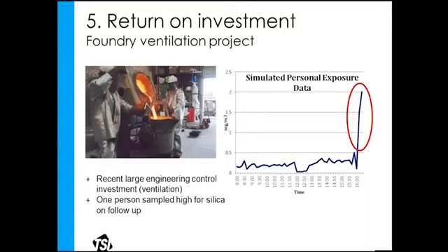And so he was the hero. He said, okay, we've got to stop doing it that way. Let's get a better tool. Let's get a vacuum. Let's get a little shop vac with a HEPA filter on it. Let's suck up all the dust instead of just blowing it around the room. So here, using real-time data, I was able to focus resources on a pretty cheap fix instead of changing again the ventilation for the whole area, which is very expensive, and they addressed the situation.